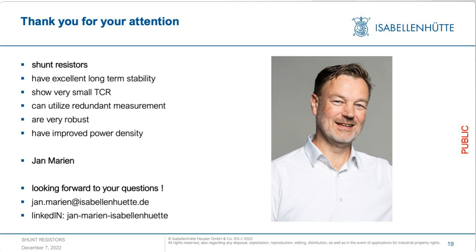How does the resistance material contribute to the overall performance of the shunt? That's also an interesting question. As I had shown in the talk, one important property of the resistance material is the TCR, and obviously this is a big contribution to the overall performance. However, as you can vary the specific resistivity, you can also have an influence on the overall material used in the design.